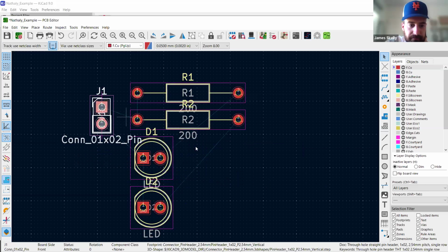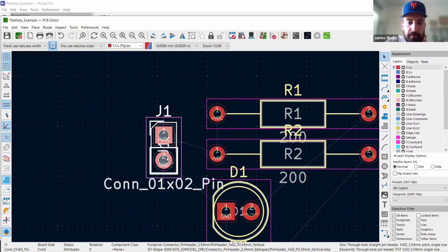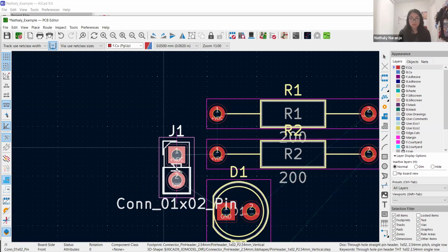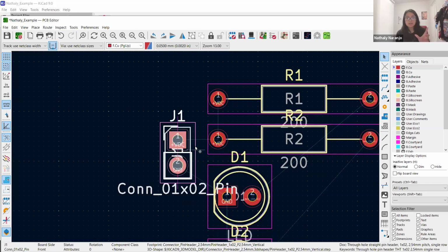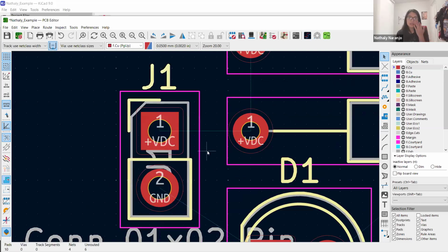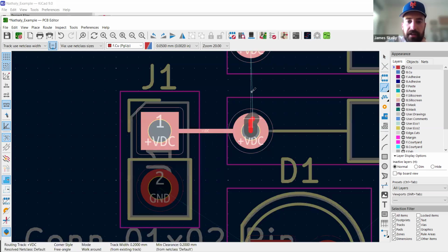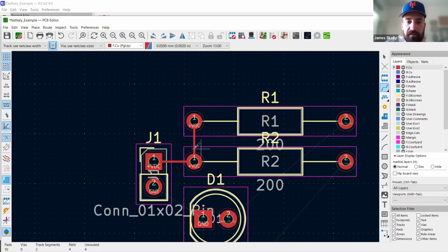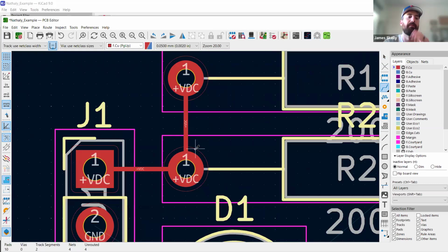And now all three of those connections are going to be right there. So the rat tails practically just simulate the connection between things? Exactly. They're just letting you know what things are supposed to be connected, and they won't disappear until you've made the correct connections. So if I connect this here, then that line goes away. And then there's one here. If I connect this up here, then that line also goes away. And once you've eliminated all the lines, that means you're done.